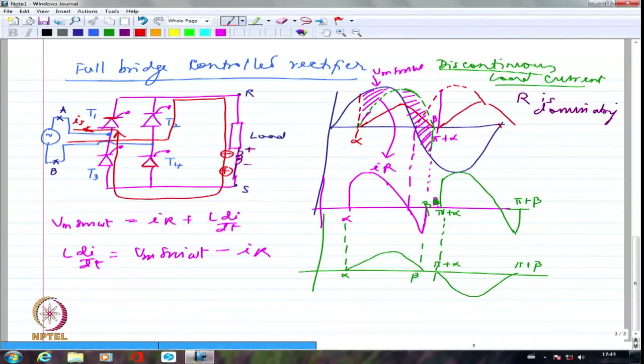Shall we go over to continuous conduction, so that we can see whether we have understood discontinuous conduction properly? This is discontinuous conduction. The current is starting from 0. If by chance I didn't have such a high IR drop, maybe the resistance is small, I am probably going to have my IR drop somewhere here, only this much.